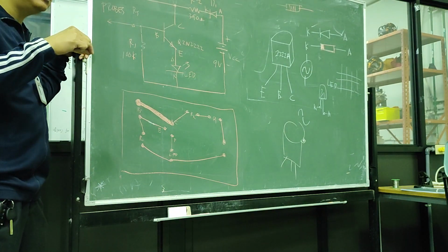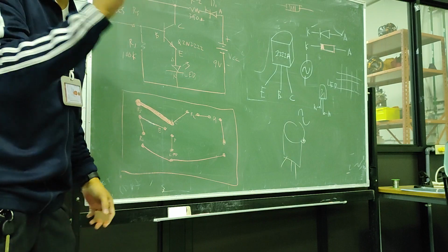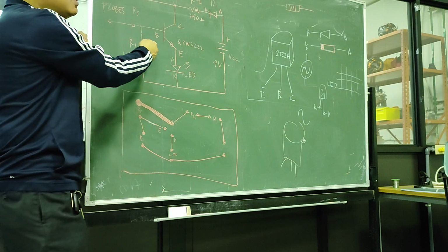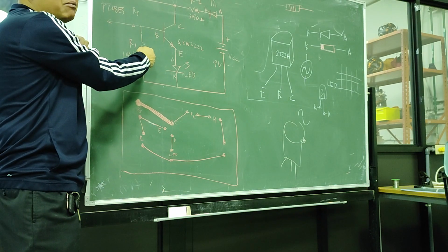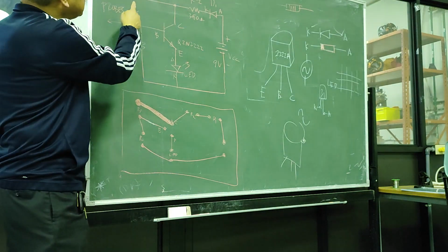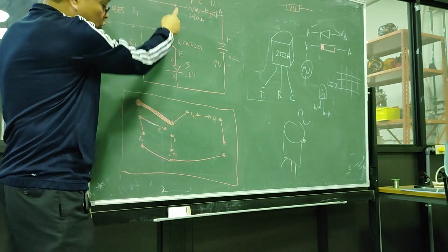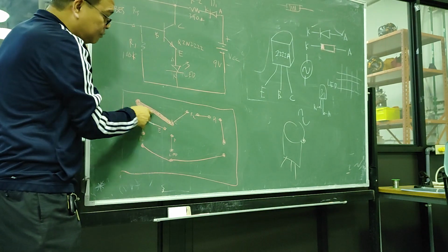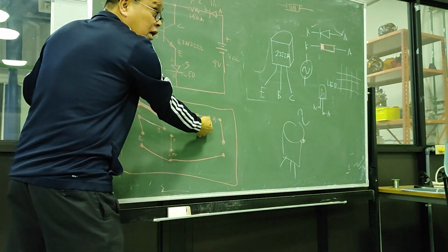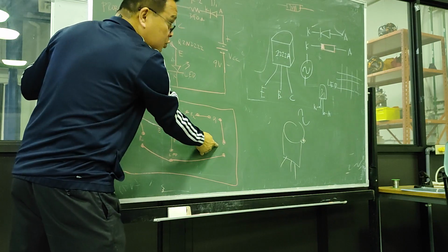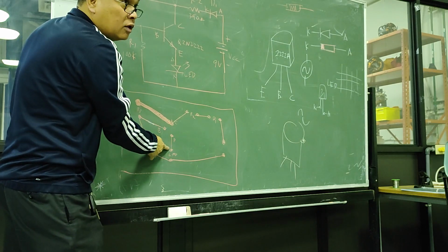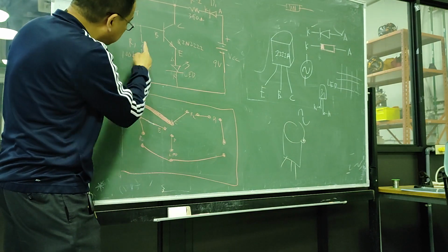After completing all the pads, the next step is to interconnect the pads. Make the connections between pads by following the connections of the diagram. It's like a simple drawing, connecting. For example, RS, this point goes to the collector. That's why here, going to the collector. Then it goes to the resistor, going to the diode, going to the source. The emitter goes to the LED again on the other side. R1 goes there, and so on and so forth.